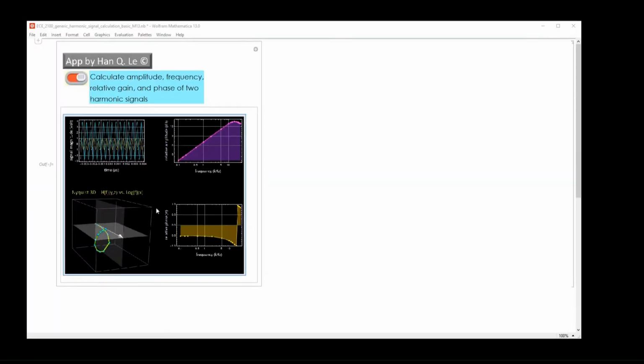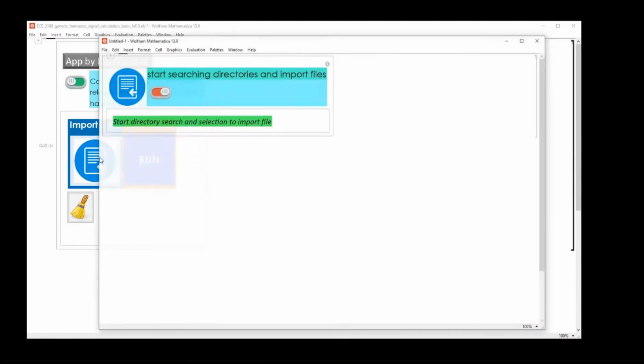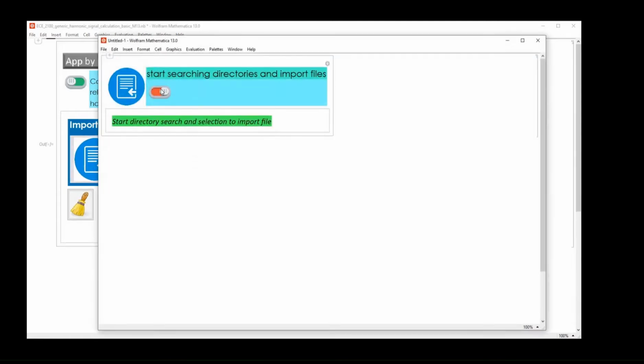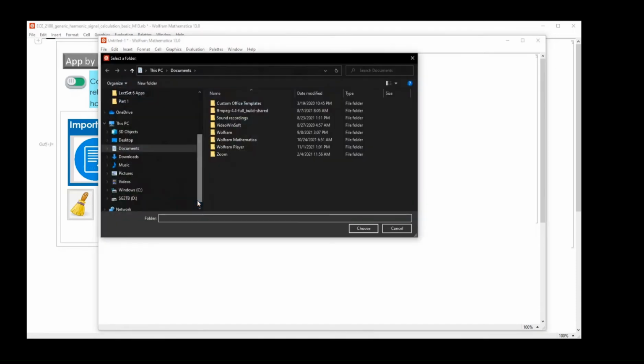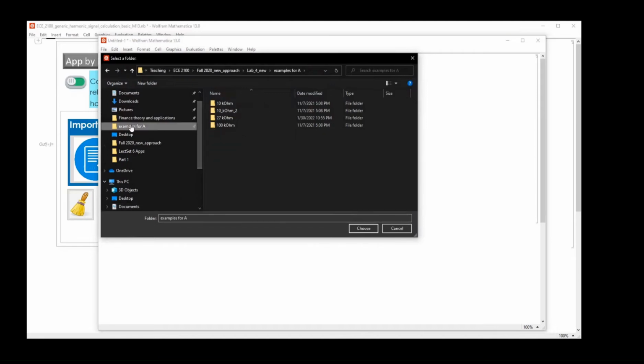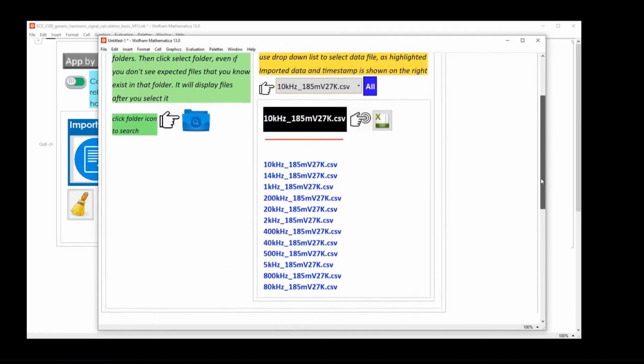This illustrates the use of an app to estimate the frequency response numerical figures from the data shown previously. The app first asks to select the data folder, then opens all the files of CSV format, which is the recommended format to save data from the AD. If all the data files listed are relevant, select Import All.